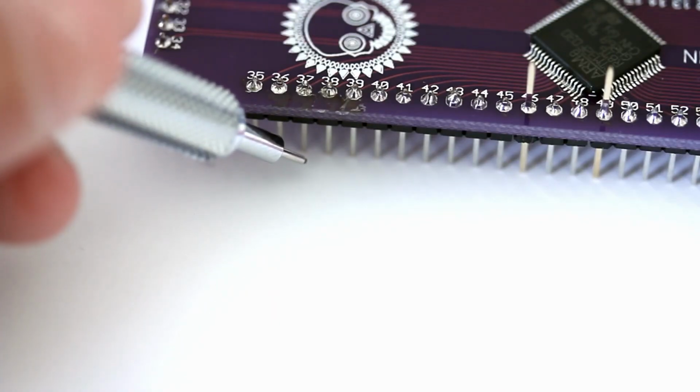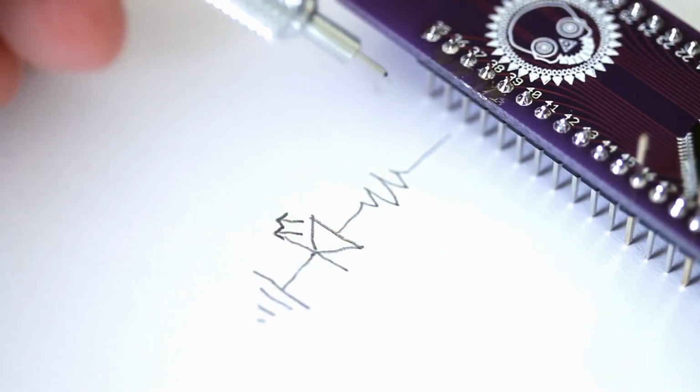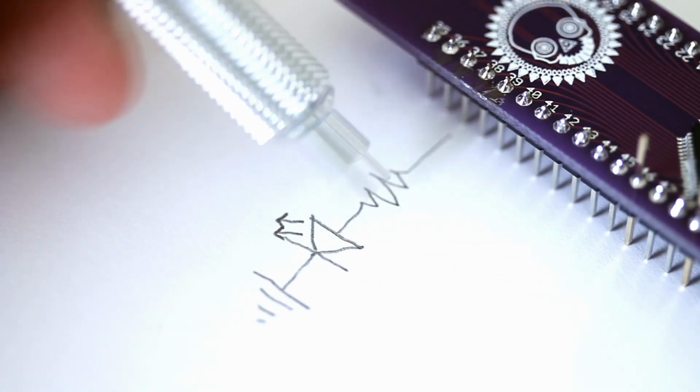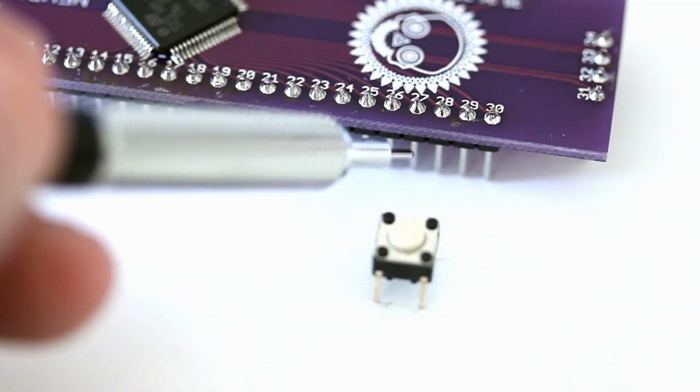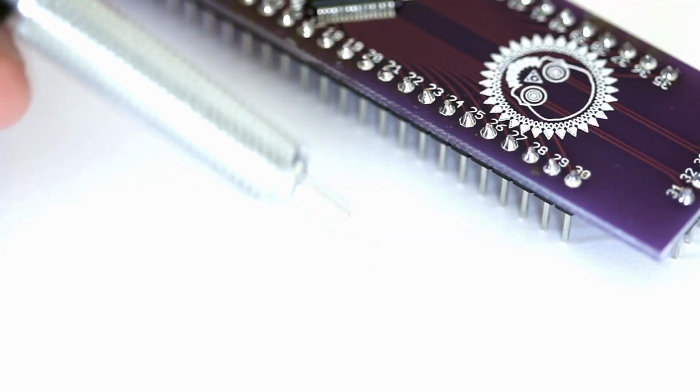As before, we'll use a resistor and an LED, and it will be connected back to ground. When we output a 1 or high to this pin, we will light up the LED because it's connected to ground. For the input, I'm going to connect the push button switch to pin number 27, which is port B, pin 1. The push button schematic is going to look like this.